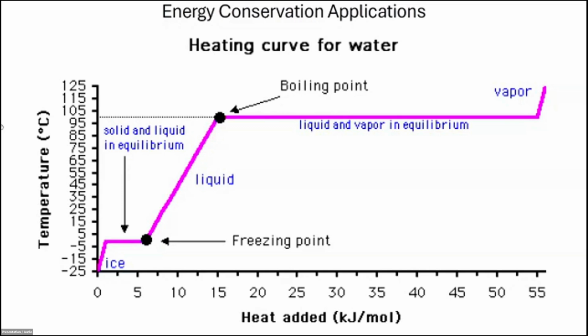The different flues and chimneys that we were using, whether they were stone or otherwise, also could not handle condensating environments. But what I want to illustrate in this graph here is the amount of energy that is available to us after the water has actually evaporated and changed phase. Many, many times, this is the energy that I'm going after in a waste heat recovery project. I want to get my flue temperatures, my exhaust temperatures, as low as I possibly can.